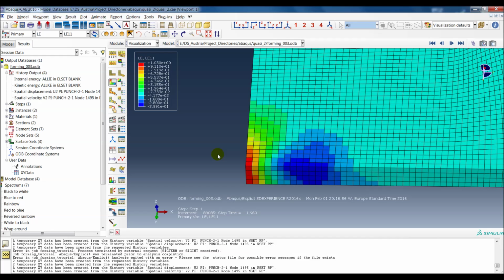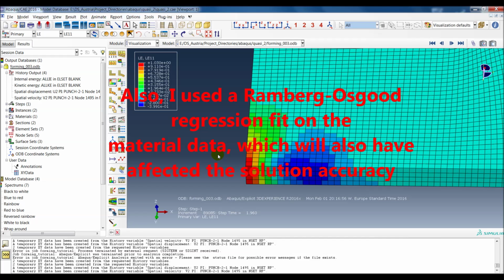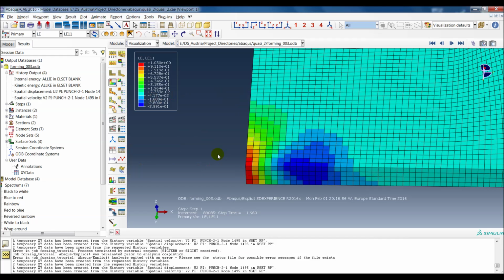So obviously we're not simulating the cracking here, and at 12 millimeters, the level of plasticity and the plastic collapse that would be taking place at this point makes it very difficult to achieve an accurate solution for this amount of displacement using nonlinear elastic properties alone. So this is not so bad. I think if we were to repeat the simulation for a lower displacement, we would probably see a much better agreement between the simulation and the experiment.